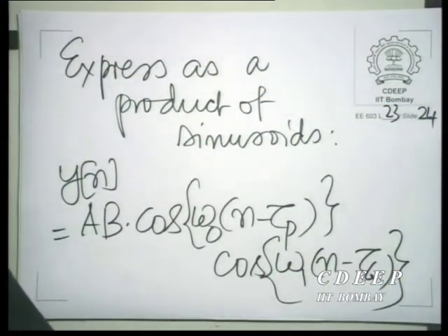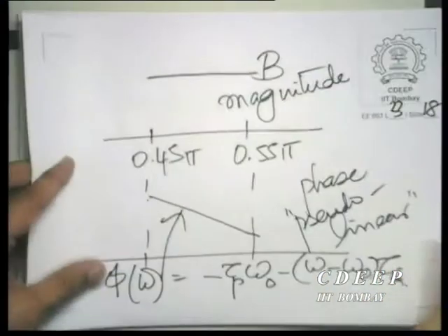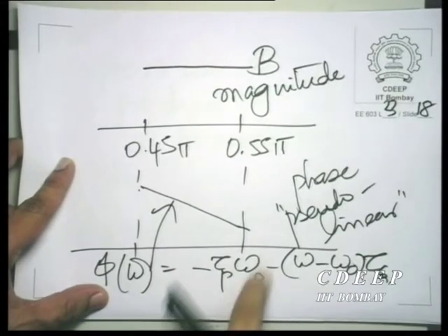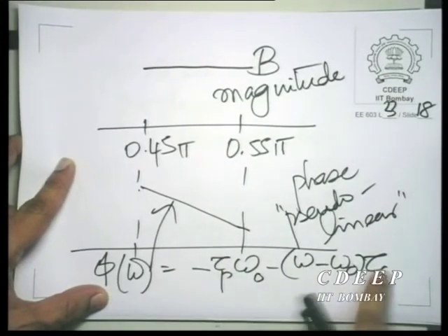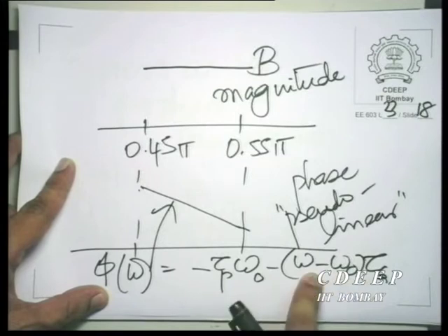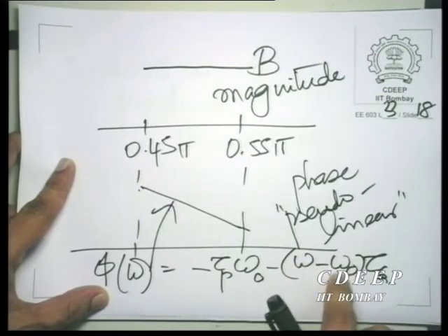Now, what it shows is that in that circumstance, there are two delays. You see, how do you construct the first term of the Taylor series? The value of the function. So, you go back to the expression that we wrote for the phase right in the beginning. The expression for the phase has a constant term here and a term which varies with omega; you are writing a Taylor series expansion around omega equal to omega 0.